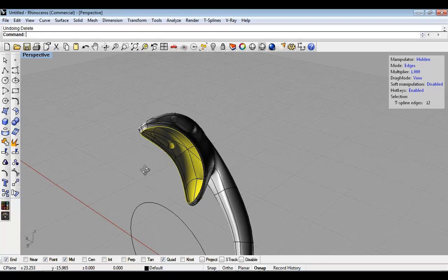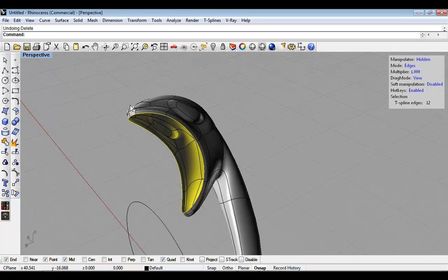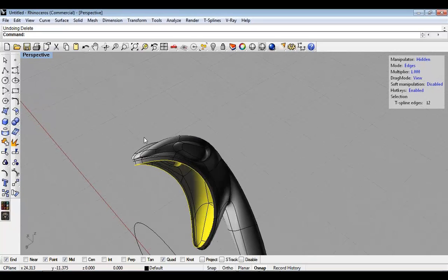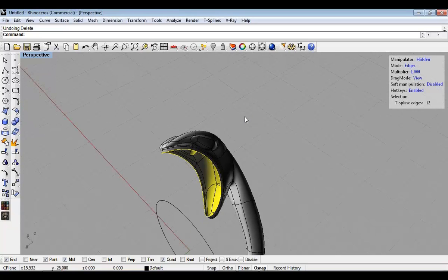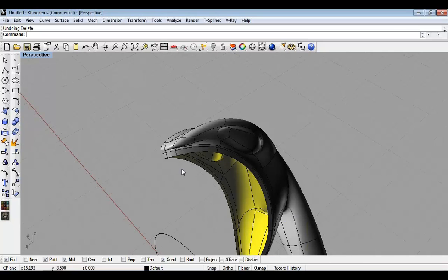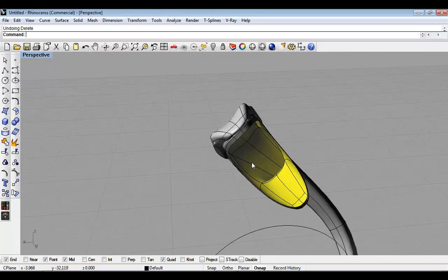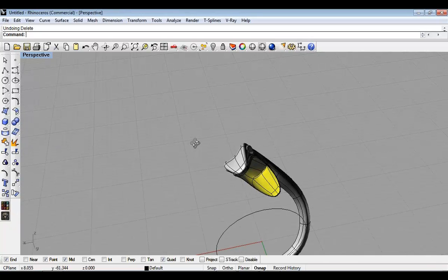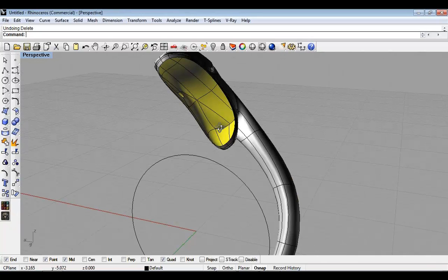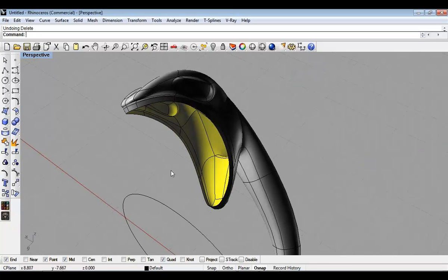Now, I'm going to try hollow this with the second piece intact. Sometimes I get a mucky bit of geometry with the hollowing actually coming through the face. If that happens, I'll try patch it. Otherwise, deleting this and scaling the head is what's going to work for us. So I've now got a completely hollow snake. I set my inside surfaces to a different color just to help me know what the inside and the outside of my pieces are. And you can do that in your Rhino options.